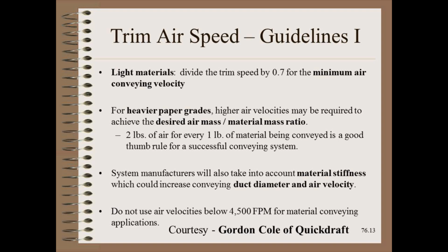As with most overspeed applications, there is little science but a ton of experience to guide design. The following are used by QuickDraft. The first thing to note is whether you have a light material, in which case you will have trim speeds approximately 50% faster than web speed, or heavy materials, in which case the recommendation is entirely different and is based on having twice the air mass flow rate as material mass flow rate.